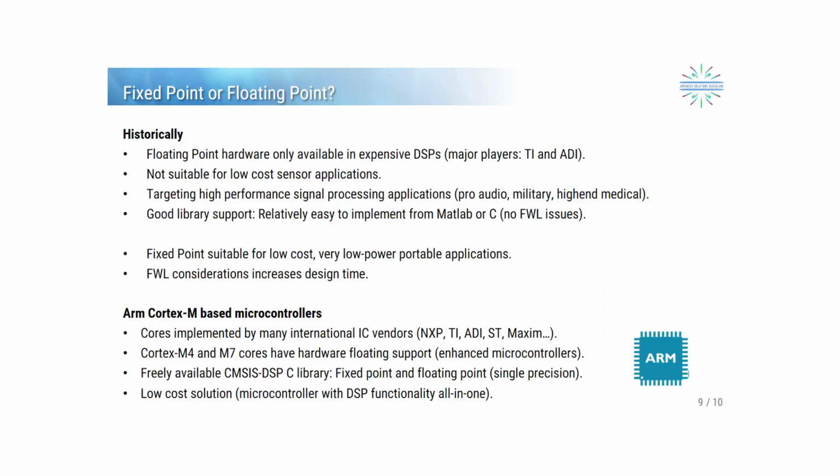One important decision that designers have to make is what type of arithmetic to use, floating point or fixed point? Looking back over the last 20 years or so, the floating point DSP market was dominated by a few industry titans. These devices were not targeted for low-cost sensor applications and were generally intended for expensive high-performance audio and military applications.